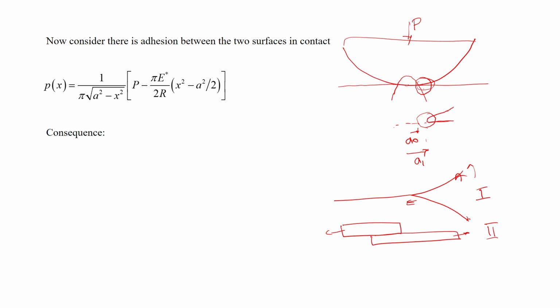So, therefore, since this particular contact edge in the context of adhesion looks like a crack tip, and there is stress concentration, we can actually borrow ideas from fracture mechanics. That is basically the idea here. So, now what is the kind of stress concentration that happens, that we can get from this equation?